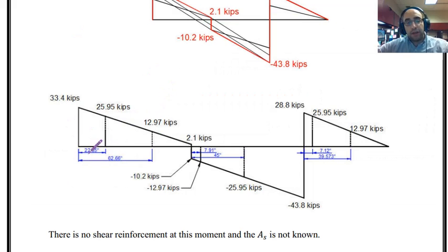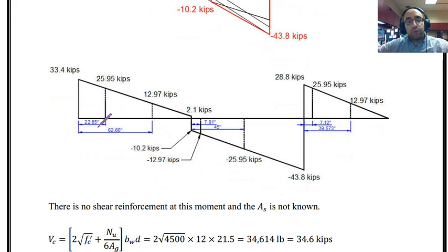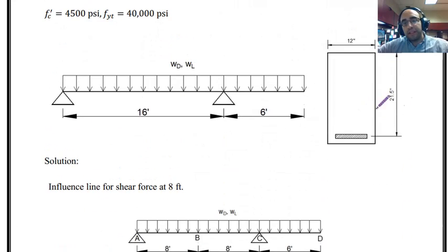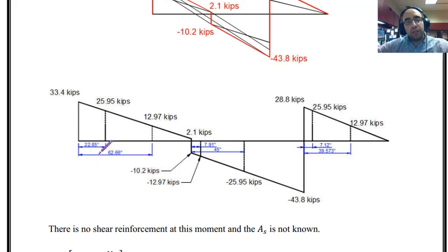In the example that I have over here, the shear we found as Vc was at 22.65 inches from the support, and it is almost d. If I look at the cross section, you can see d is equal to 21.5, and the shear that we found as Vc was 22.65. So it is just about 1 inch difference, and we can say we are approximately there. So based on these close values, I can say I don't need to find the shear at d inches from the support, because that will be some point very close to this value. And that means we can say in all of these regions that we have, which are almost d inches from face of the support, we can just extend the reinforcement that we have in these regions to the support. And this is how it is always done.